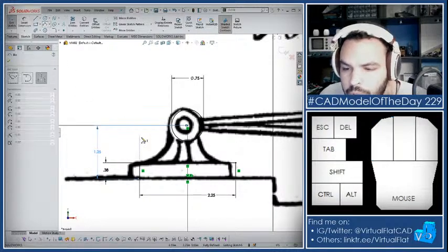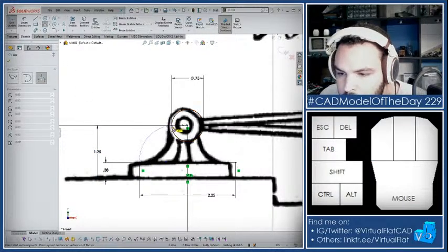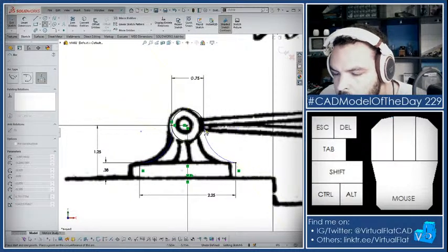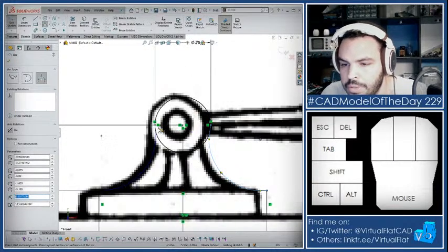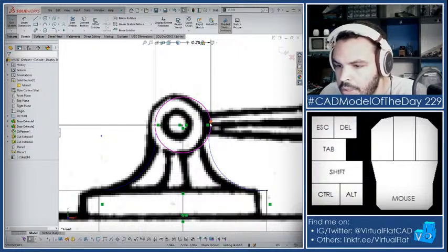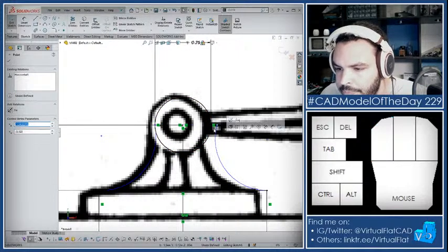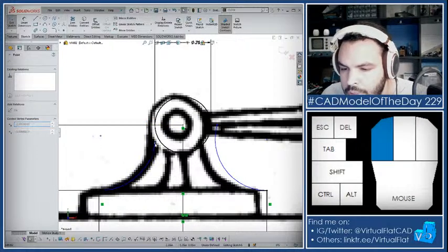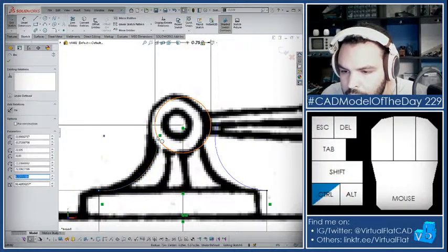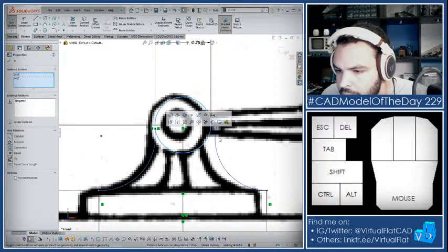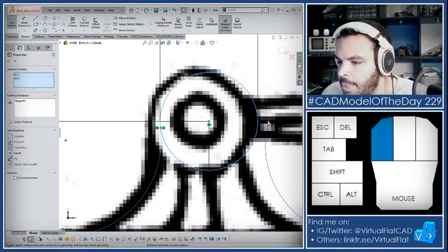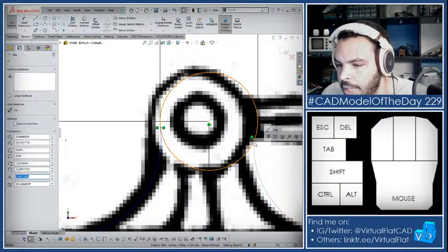All right, so I think a couple of arcs will be pretty good. Maybe something like this. Yeah, and I'm snapping to those midpoints, so it's not going to be exactly tangent. That actually might mess me up. Let me get rid of those. And also picked up a horizontal. And do that and say this with that tangent. Okay, yeah, because if I put it all the way up, there's going to be a tiny little overlapping area. That's just going to ruin my day.